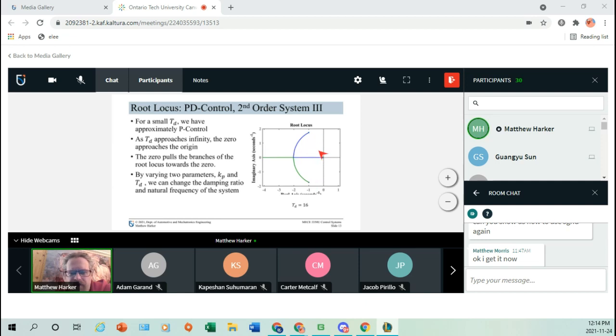But basically now if we had our S grid on here, we'd say the angle of the point would define the damping ratio, and its distance from the origin would be essentially the natural frequency of the system, right? So here we can't change the natural frequency, because we're fixed on that radius there.